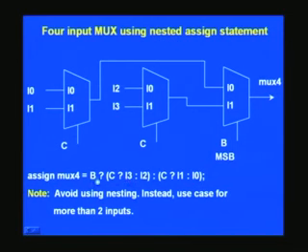To make it more clear, let B select this, this is the MSB we have seen. If you notice here, I0 I1 is coming over here as the output of the first mux, and the second mux output is derived from I2 and I3 here. So by selecting B, for example, if you make it 0, then this will be selected. When this is selected, which of these will be selected depends upon C here. So naturally you can very easily select one out of the 4 signals as such.